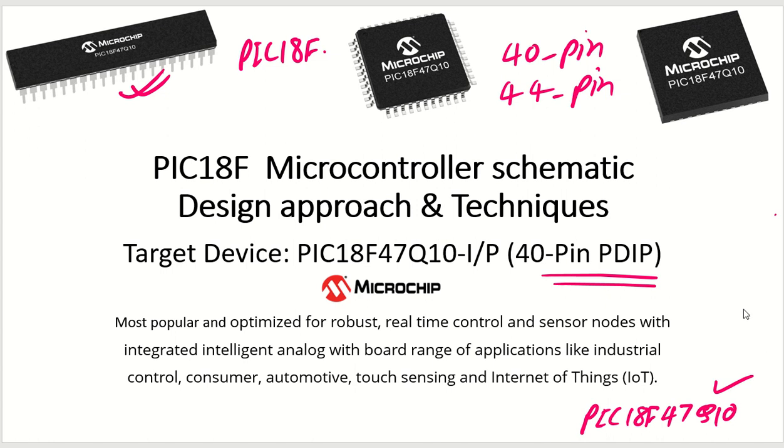In our next session for this microcontroller, we'll try to understand some basic applications of UART, like RX and TX pins, as well as the SPI interface. Let me just tell you, SPI connections will require your MOSI, MISO and slave select or SS pin, or chip select pin, correct?